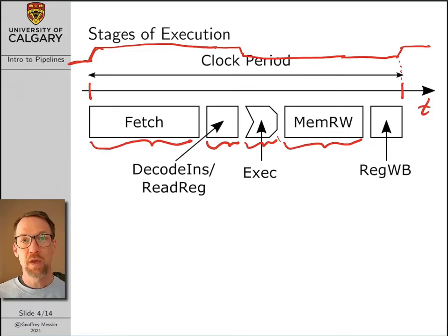For example, the ARM microarchitecture has a register that holds your address, just like AVR. But then you can also optionally add a little offset in the machine language instruction that needs to be added to the register before you can access memory. And the ALU does that addition.